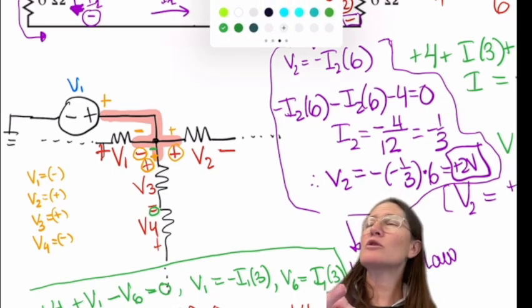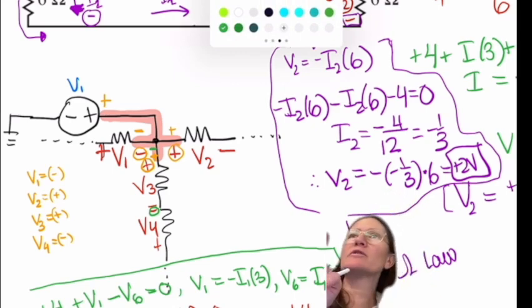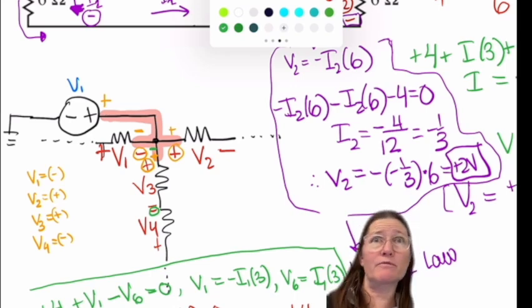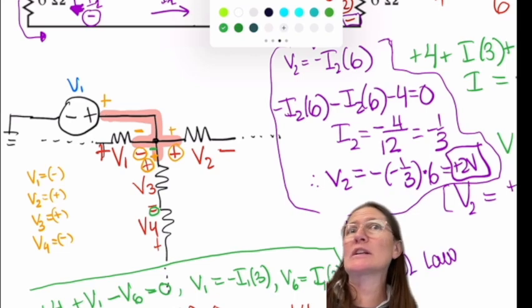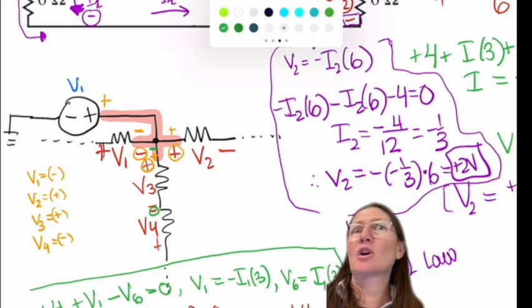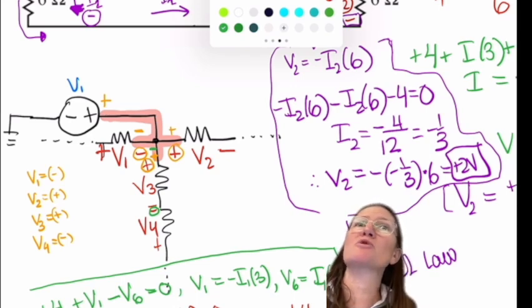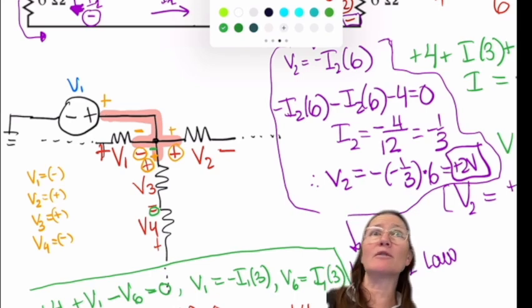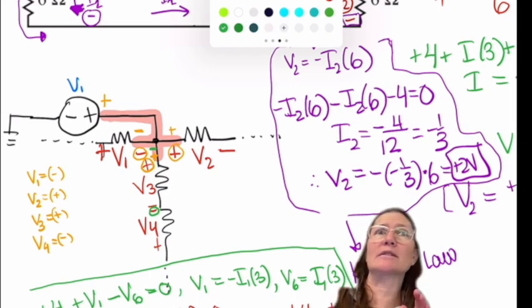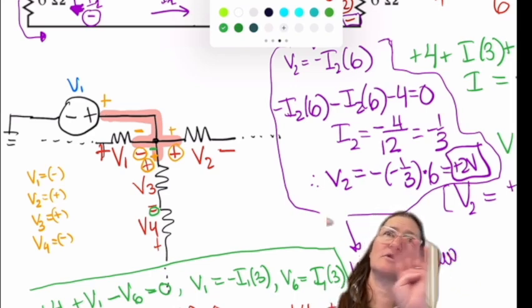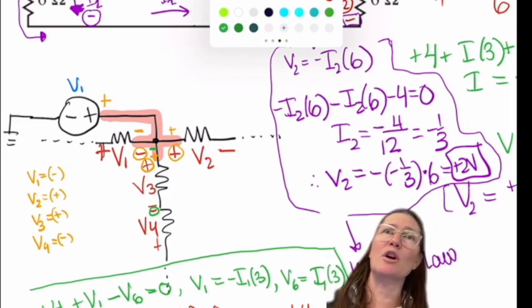Okay. So the question, if you didn't hear all of that, was about the R total that you have on the bottom of the voltage divider. How do you know which terms to put into that R total? It's going to be determined by whatever's in the branch. So if you have 4 resistors there, your R total would be all of those resistances added up. So you would have 4 terms added up in the bottom for R total.